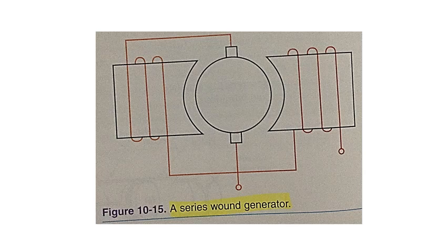A series winding by itself will provide a fluctuating voltage to the generator load. As the current increases or decreases through the load, the voltage at the generator output terminals will greatly increase or decrease. Because of the wide difference in output voltage, it is not a very practical generator to use if the load varies.